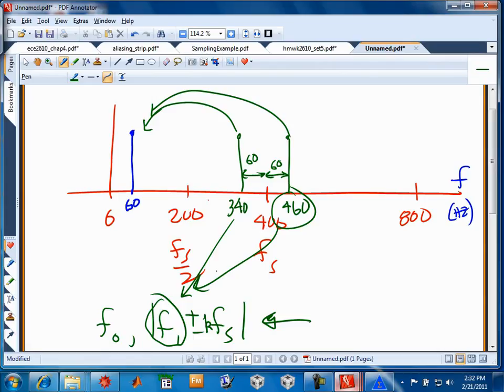So now we're looking for yet another possibility that can go into there in place of F1. We might call that F1, and F2 is what we found. Suppose this is F naught. This would be like an F1 and this is an F2. They're all equivalent frequencies with regards to the 400 hertz sampling rate. So now for a different value of K, I can find another pair of frequencies, say F3 and F4, that will be above and below, say, 2 times Fs. See what I'm getting at? So you said 740? Yep.